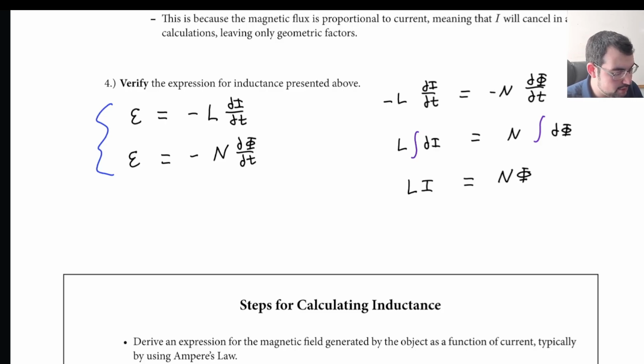A lot of people actually like this as the inductance formula, because it makes an analog to momentum. We said that 1/2 L i squared is sort of your kinetic energy. Well, L i is your mass times velocity, or your momentum. So it makes sense, because Faraday's law says that a flux change is required to induce an EMF. This is similar to saying a force is needed to change your momentum.